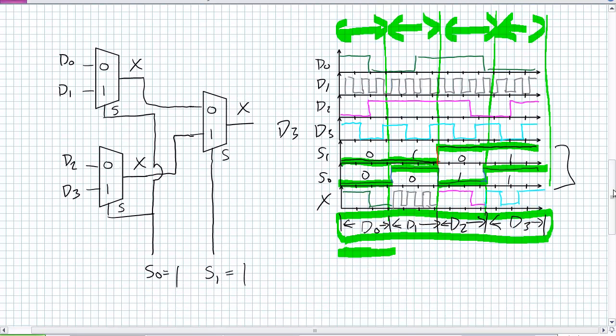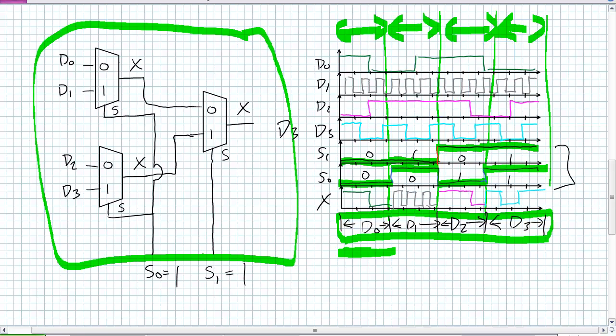When I make a 4-to-1 multiplexer using 3 2-to-1 multiplexers, how many components am I using? Trick question. How many instantiations of components am I using? Are there any internal signals that I might need to declare? Okay, so think about that. What I'm referring to is obviously this picture right here. How would I do a port map to those component instantiations? Again, potentially using internal signals. So think about that, because I'm going to throw something at you.